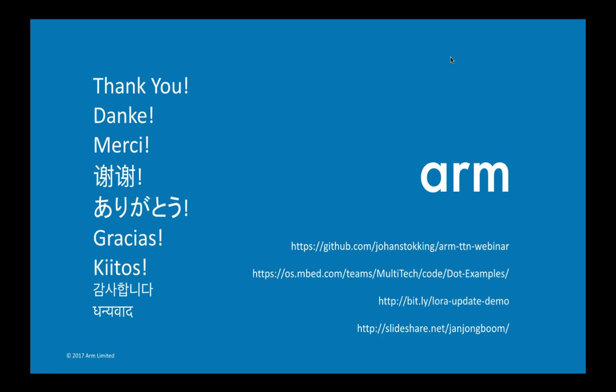Currently the technical committee of the LoRa Alliance is very close to releasing the specifications of how this all works together. But Jan and I did a demonstration, and the third link on this slide brings you to an article and a video where we demonstrate firmware updates over LoRaWAN. We have a reference design of the firmware running on a Cortex-M3 with 32K RAM that implements this spec, and it also implements delta updates over multicast. It's licensed under the Apache 2 license. So when the spec comes out, and the first network servers support it, Mbed will be the first platform that supports this.